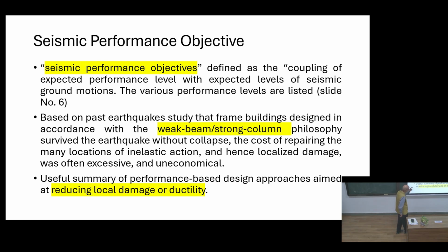So let us come to the pushover analysis, where the plastic hinge is the important part of the structure. You have to design the structure in such a way that the plastic hinge forms at a predefined location. As I said, at the initial design level you can define where you are allowing damage in the structure, and later on you can repair or retrofit it. Those damages come into the picture in the form of plastic hinge rotation.